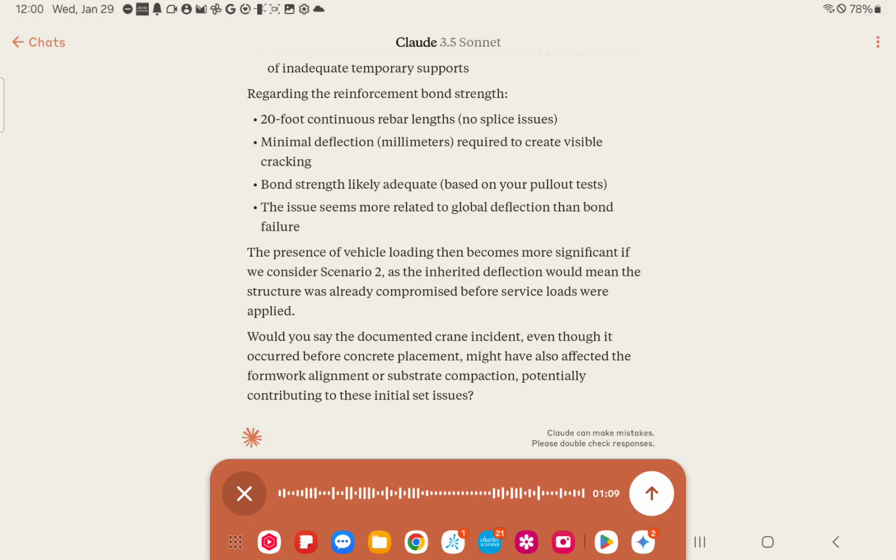They did not look at that deflected section and inspect it properly when they removed it. That created an evidential problem to confirm that the fracture started right along that line. But the images before they did the demolition show this butterfly deck failure location right down there. It shows that that's where the deflection was, both sides coming in, both sides of this 21-foot span.